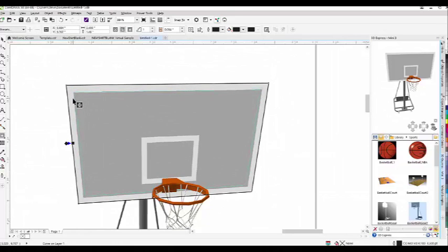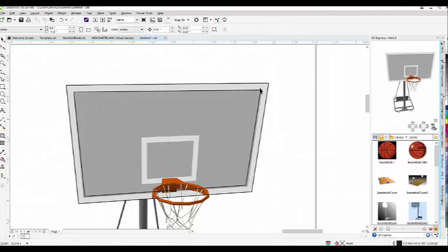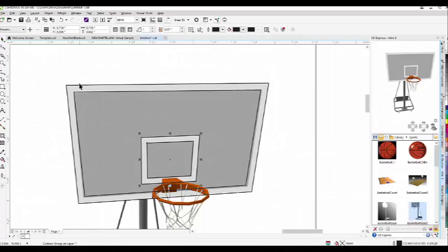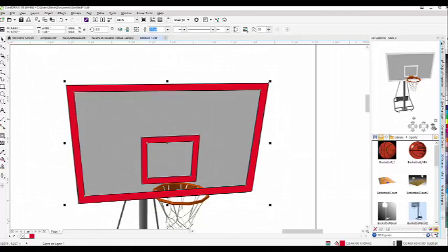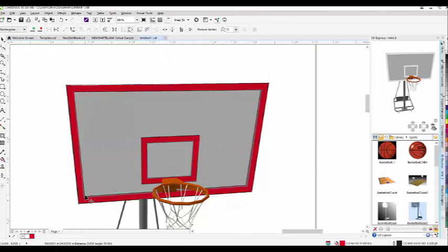Use the contour tool. An inside object. And I'm going to break that apart using the keyboard. And we're going to get this inside part. Now I'll use the contour again, break that group apart with the keyboard. And we'll select the entire thing and then combine it. And I'm just going to add some color here so you can kind of see what I'm doing. I'm going to move it to the back, and as you can see, it's transparent, semi-transparent.